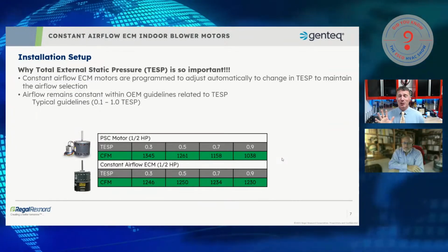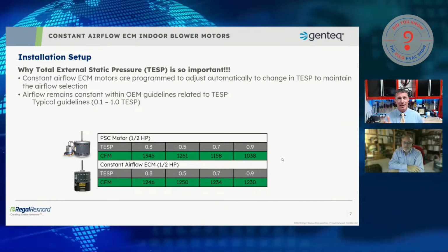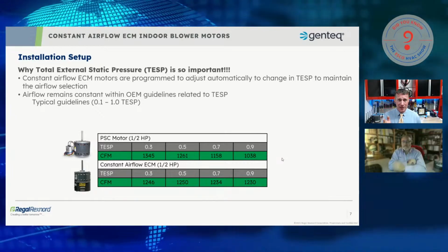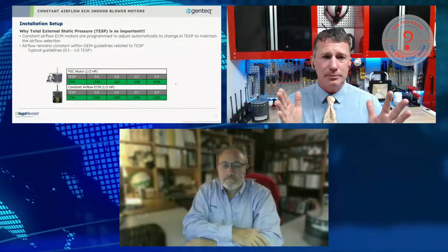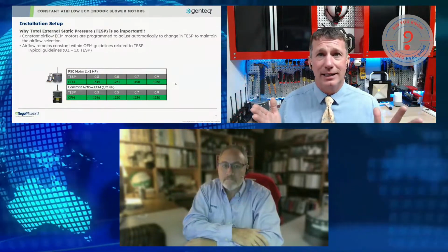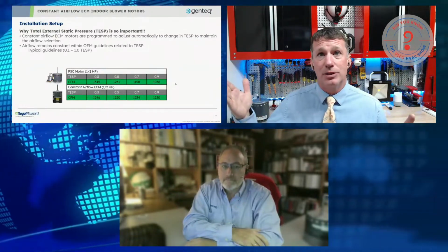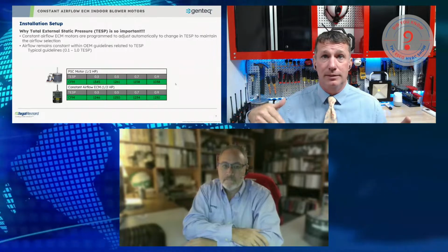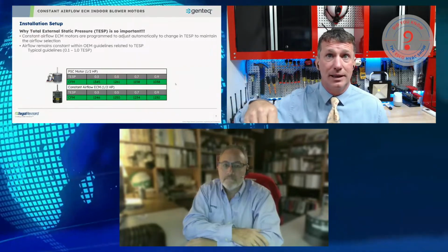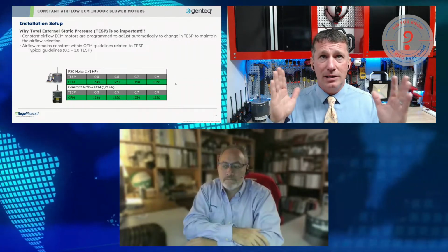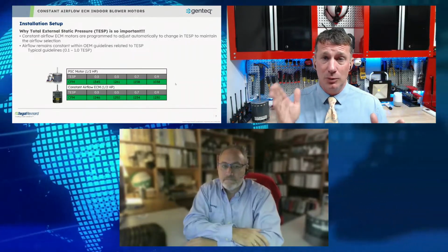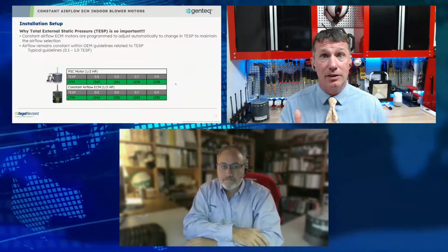Not to say that it would ever do that, but I would threaten my contractor so that they understood that previously, if you had an external static pressure chart and you knew that you were getting to the high end, you knew that if it got any higher, it was going to start diminishing airflow even more drastically than it had before. With all of our ECM motors, that range matters, because we know if we get above that range, we are going to have consequences.